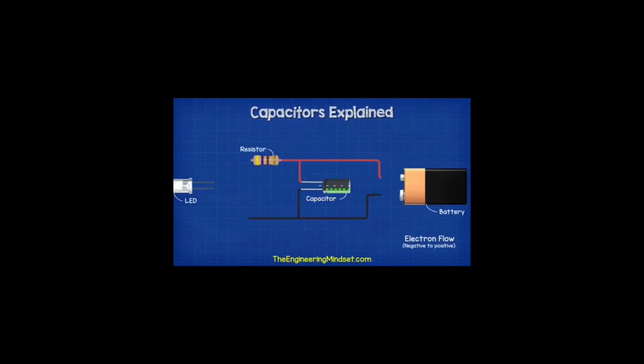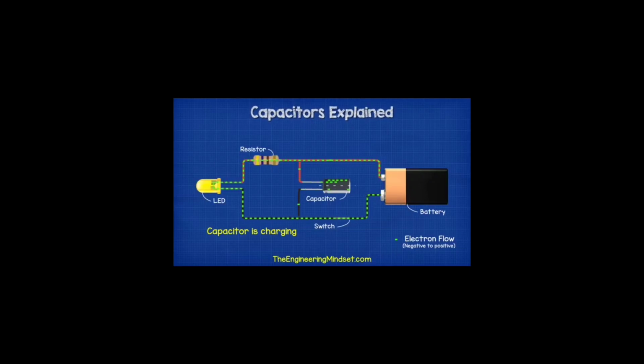If we then place a small lamp into the circuit, a path now exists for the electrons to flow and reach the opposite side. So the electrons will flow through the lamp, powering it, and the electrons will reach the other side of the capacitor. This will only last a short duration though until the build-up of electrons equalizes on each side. Then the voltage is 0, so there is no pushing force and no electrons will flow. Once we connect the battery again, the capacitor will begin to charge. This allows us to interrupt the power supply and the capacitor will provide power during these interruptions.